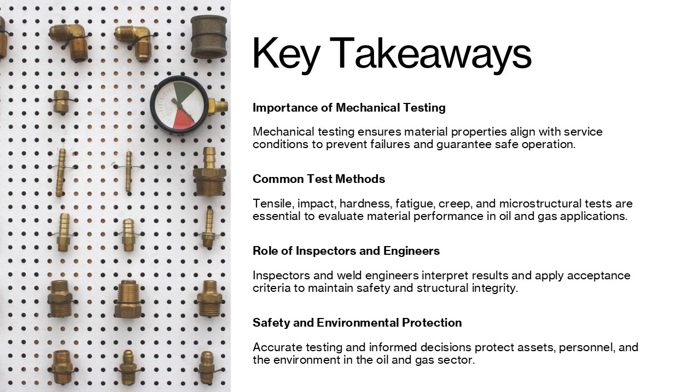Inspectors and weld engineers must understand how these properties correlate with in-service behavior to prevent failures such as brittle fracture, fatigue cracking, and creep deformation. By mastering mechanical test methods, interpreting results accurately, and applying acceptance criteria correctly, inspectors ensure the safe operation of pressure equipment, pipelines, offshore structures, and welded assemblies.